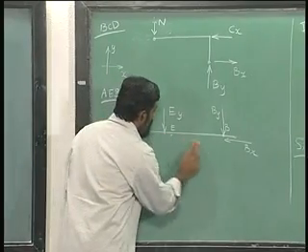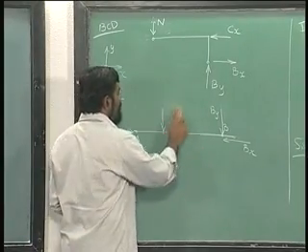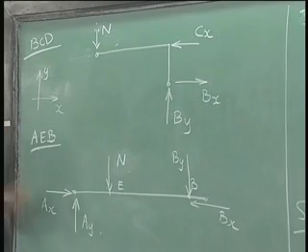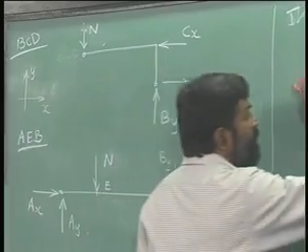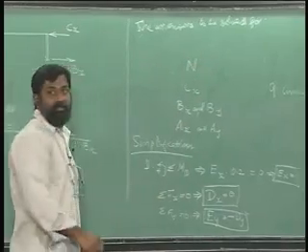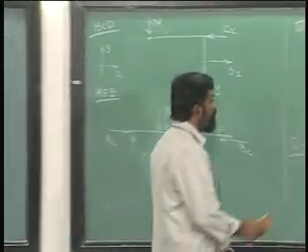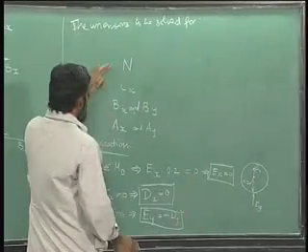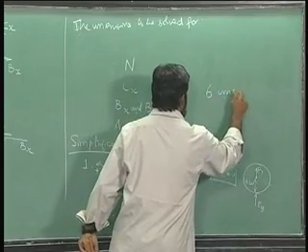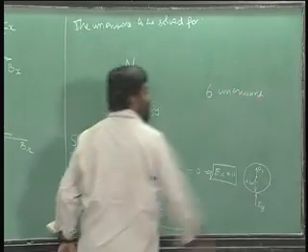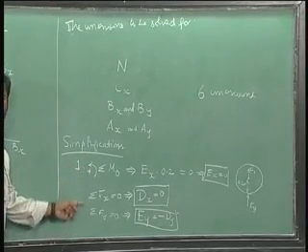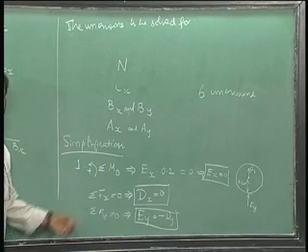Here also I do not have this Ex, this is nothing but the N acting from the wheel. Now, we have reduced it, we do not have this anymore, instead it is replaced by a single unknown N. Now, instead of 9 equations we have 1, 2, 3, 4, 5, 6 equations to be solved. Okay. Mind you, in doing that we have already used up all the 3 equations necessary for the wheel.